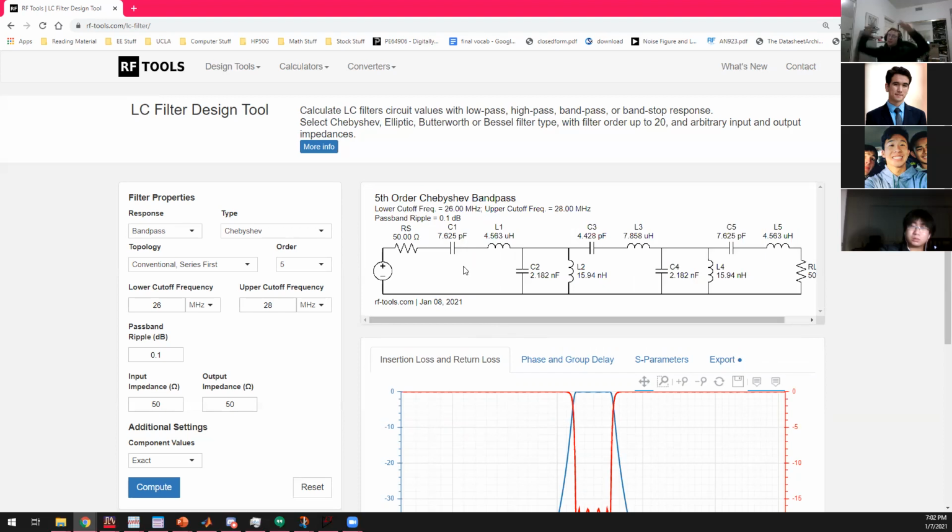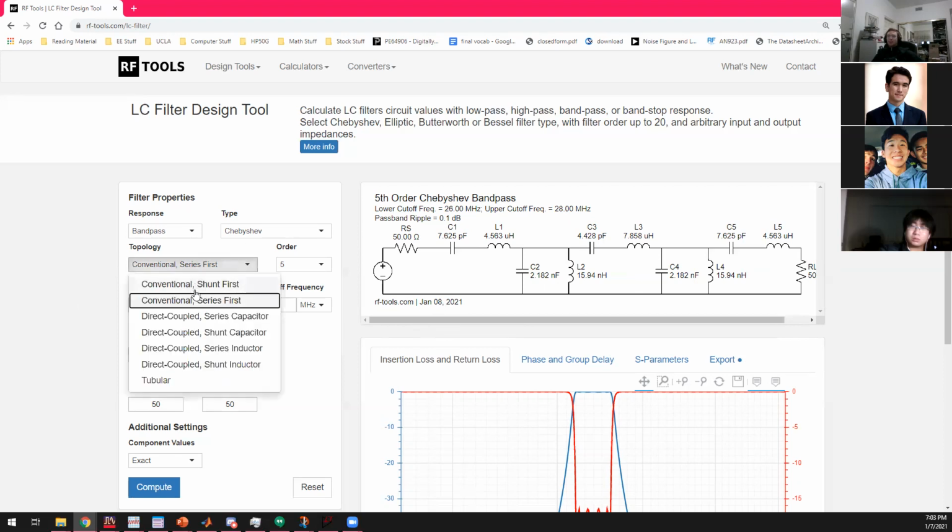And that could allow you, if you had this on something like the output of an amplifier or an input of an amplifier, to get rid of the coupling capacitor that you usually have there, like the one that separates DC from AC. So you could actually use a filter to separate DC and AC. So that's just a little technique to use.